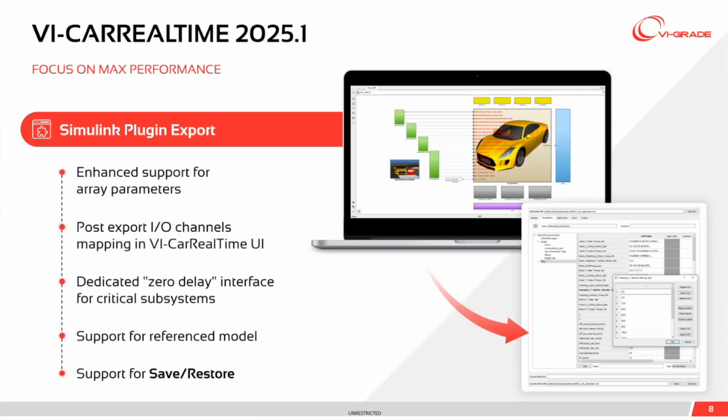With the latest version of VI-CarRealTime, we have introduced several enhancements to the plugin export from Simulink, suggesting a new workflow to incorporate complex Simulink model in VI-CarRealTime. For instance, we now have support for a wider variety of models, including those that use reference model and subsystem that were not supported in the earlier version of the software.